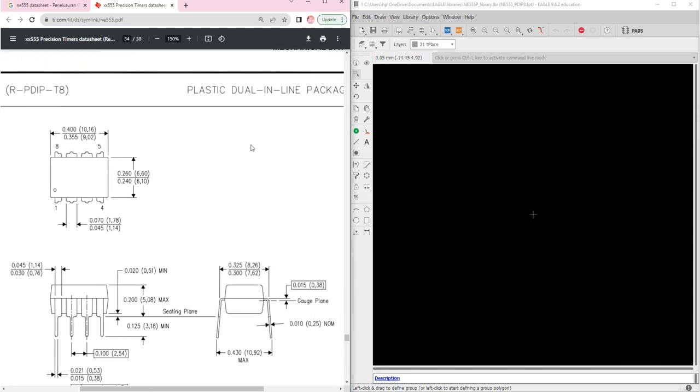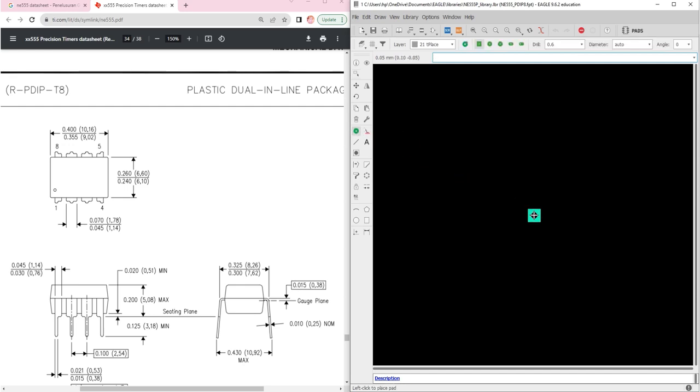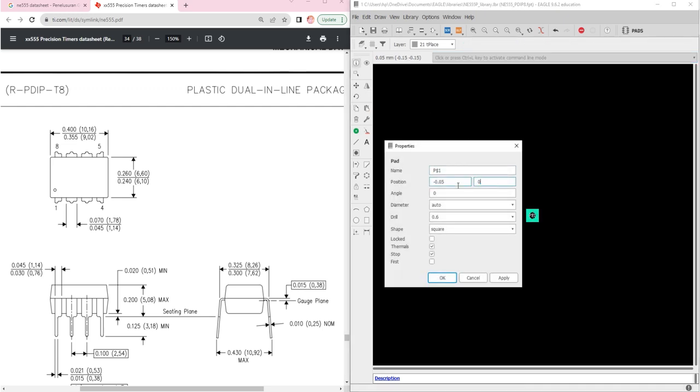First, we will need the paths for our footprint package. Since we will be making a through-hole footprint, we're choosing this green icon here. If you want to make a footprint package for an SMD component, then you can use the icon next to it. To edit the path, click this information icon here, then click the path to show the properties of this path. You can edit the parameters here.